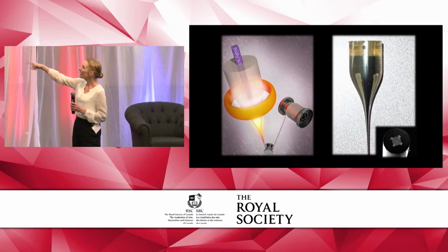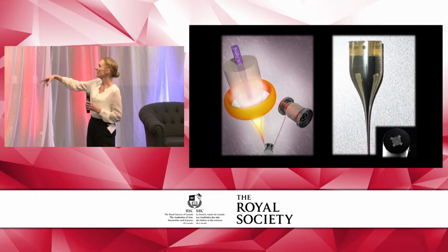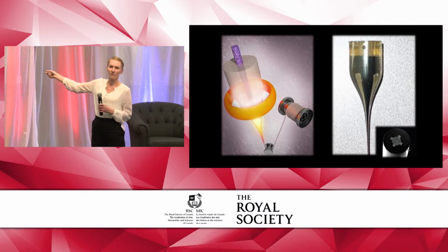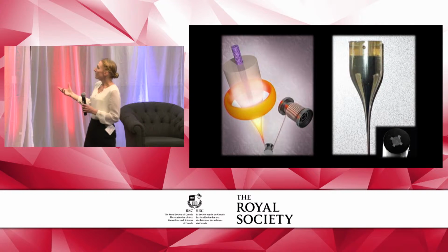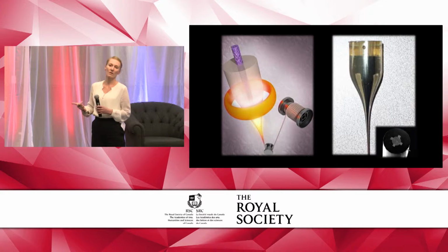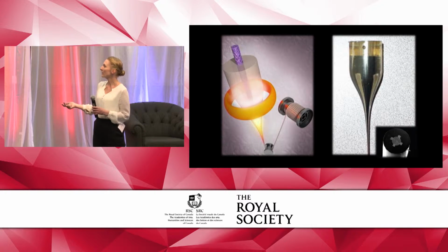Hopefully when the next slide comes up, you'll see that we have the fibre drawing tower, we have a heating element, and then we draw our macroscopic preform down into some sort of microscopic scale. Now, in order for this to work, we need to make some careful choices about our materials and also about the draw speed and the temperature we're using.